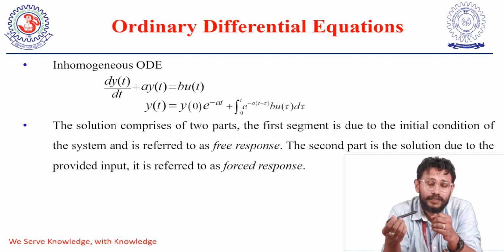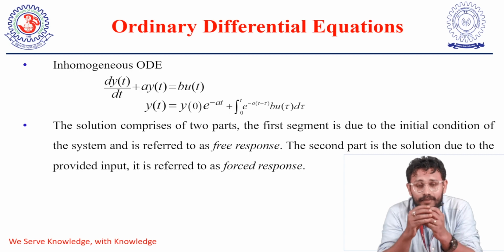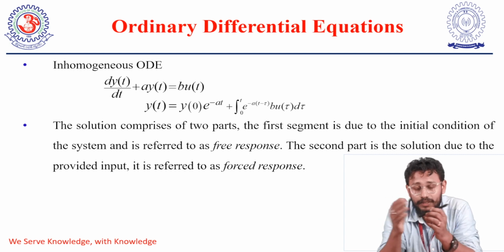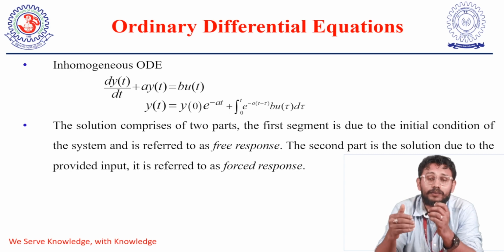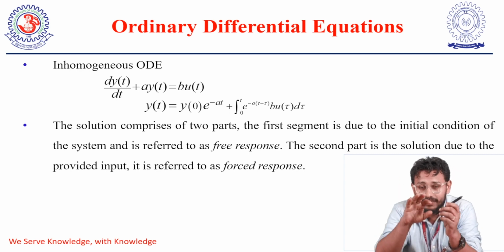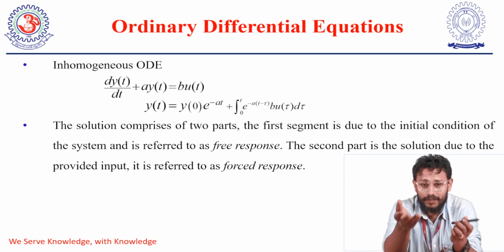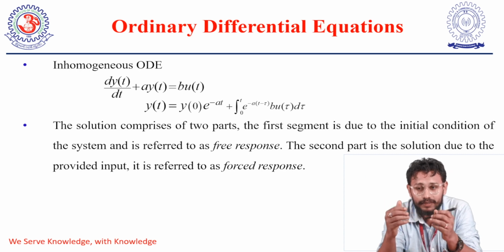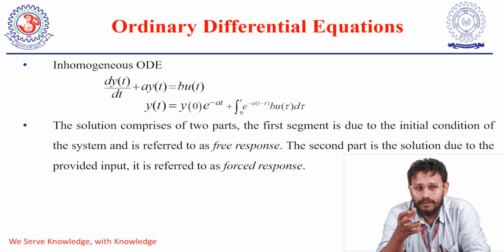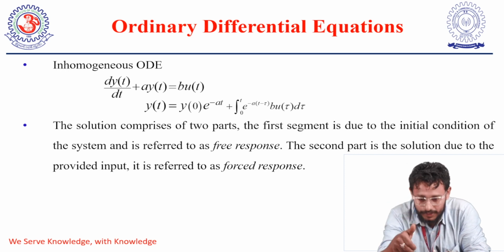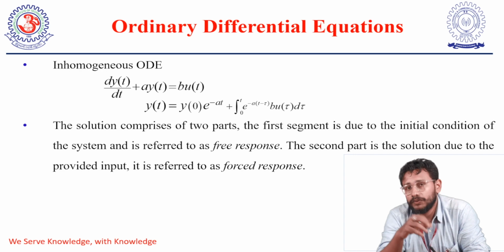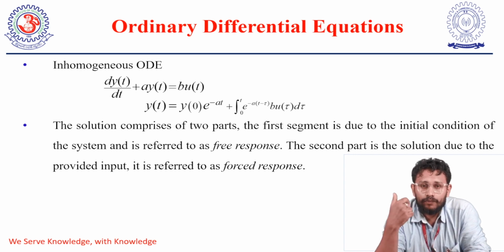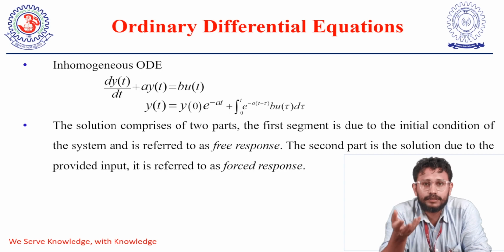the engineer would be designing the vehicle in the form of a mathematical model, some form of ordinary differential equation, and he will be applying certain sort of input, wherein this input is a change in the state of the system. That may be a bump in a road, or maybe you're speeding suddenly. Now, this is the moment where we talk about different forms of inputs in the system that we'll see in this lecture. But as of now, we're just supposed to understand that once a system is defined mathematically, before hitting the real world, the designer is aware of how well the system is supposed to perform